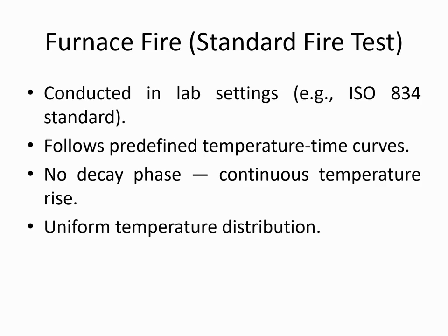In component fire, we have three phases: first one is growth, second one is post flashover, third one is decay phase. But in furnace fire, there is no decay phase. The furnace environment provides uniform heat, allowing consistent comparisons of materials and systems.